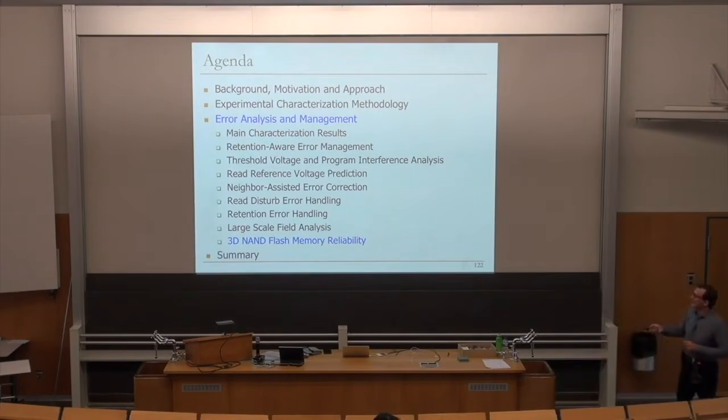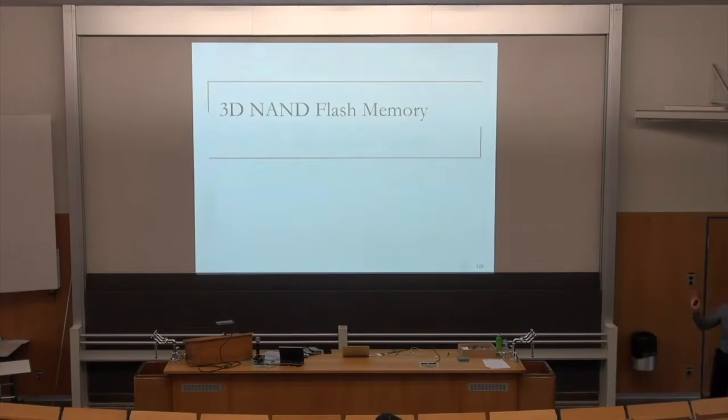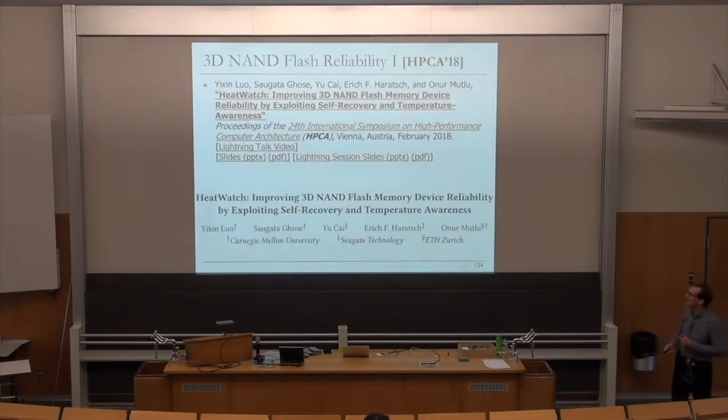And as a result, similar techniques are going to be employed in those controllers in a much more efficient manner. Okay, so let's talk about 3D NAND, because so far, all of the data that I presented is from 2D planar NAND. And it's very interesting still, and it's going to be even more interesting, especially when 3D NAND scales down to smaller feature sizes. And at some point, flash manufacturers were very limited in terms of planar flash memory. And all of these error studies are extremely important, and they're still very important. But 3D NAND relaxed things a little bit and changed things a little bit. And we're going to talk about that, because it enabled another level of freedom, which is the 3D stacking nature.